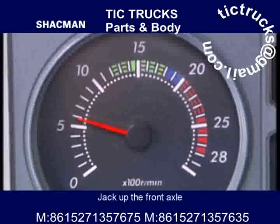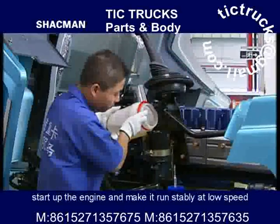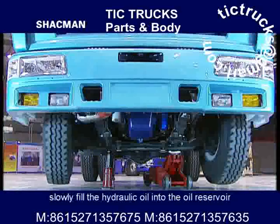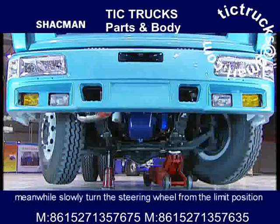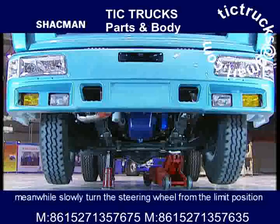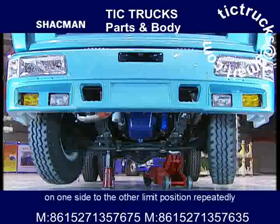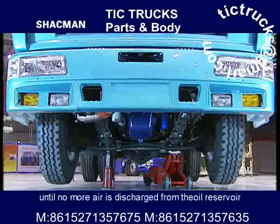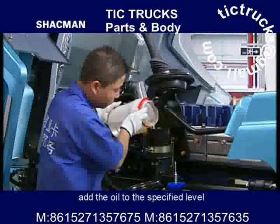Check up the front axle. Start up the engine and make it run stably at low speed. Slowly fill the hydraulic oil into the oil reservoir. Meanwhile, slowly turn the steering wheel from limit position on one side to the other limit position rapidly, until no more air is discharged from the oil reservoir. Add the oil to the specified level.